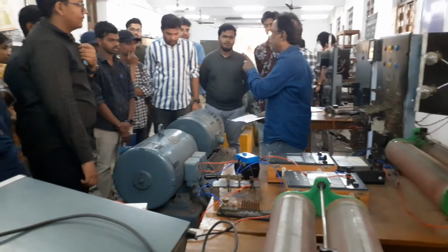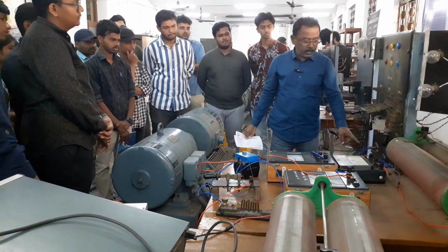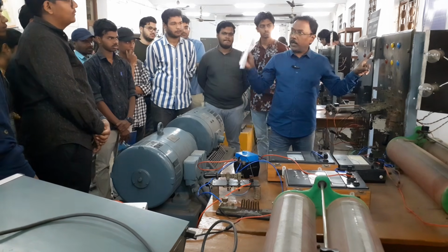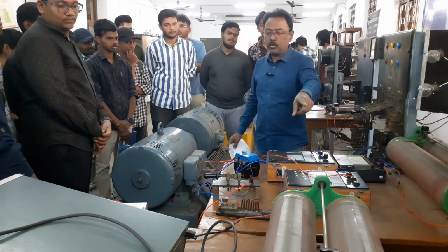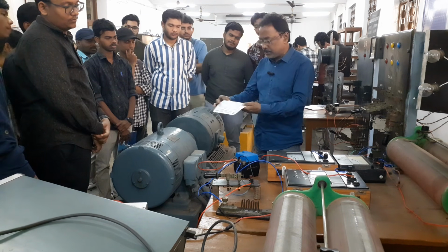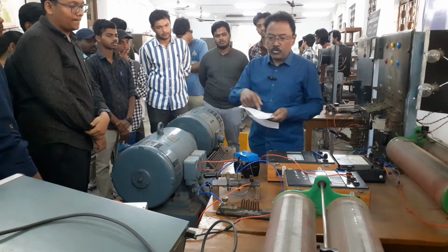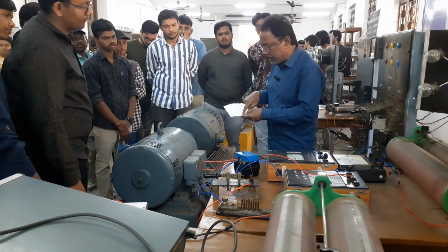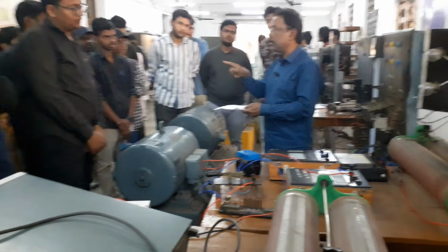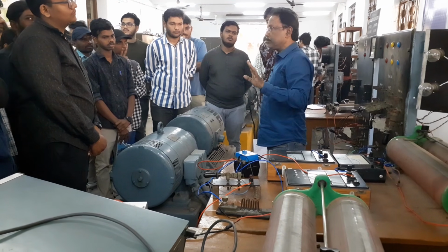Clear? Any problem? Three-phase alternator. These are the field connections of the alternator, as you have already drawn. Then we have to measure the frequency and adjust it to 50 Hz. Then the voltage should be 200. In that condition, we will energize this three-phase contactor by 230 AC. If you close the switch, 230 AC will be fed, so just make it on and off. At that time, we can store the waveform, if your storage mode is activated.